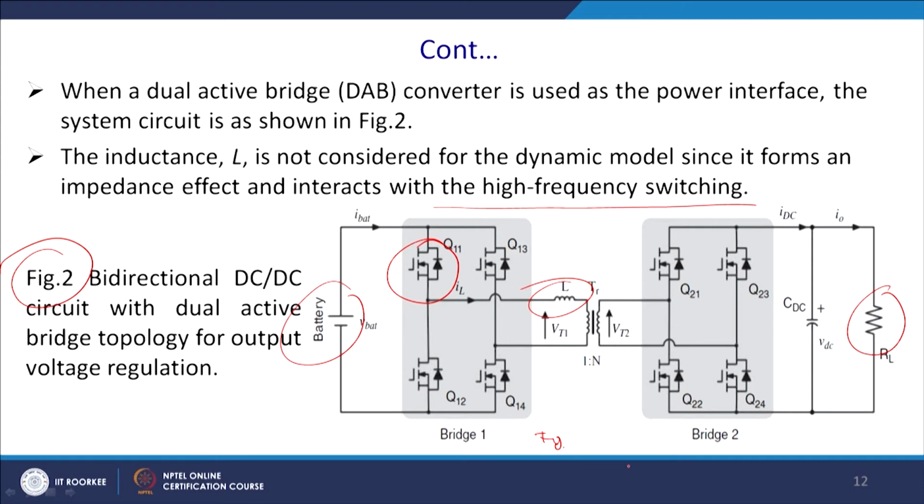But if it is AC, with solar and battery feeding a microgrid, there will be an instantaneous variation of double frequency, and maybe that current is fed from this battery instead of the load, and thus bidirectional flow is possible, and also maybe this capacitor itself can handle that power and send back the power, and then there will be a ripple in the capacitor.